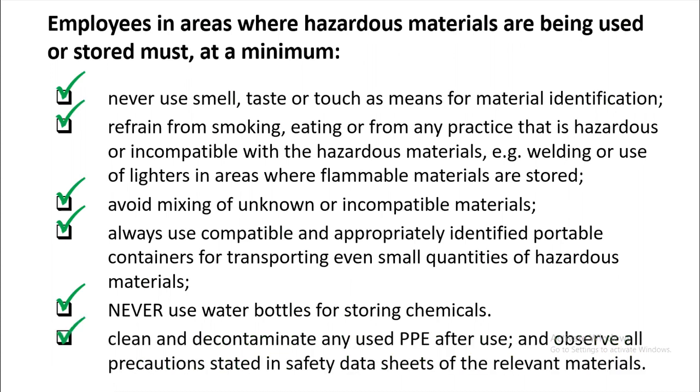Clean and decontaminate any used PPE after use. When you use PPE, for example the coverall and your hand gloves, always decontaminate after use, so that when you use it again the next day, you are safe to use it. And observe all precautions stated in the safety data sheets on the relevant materials.